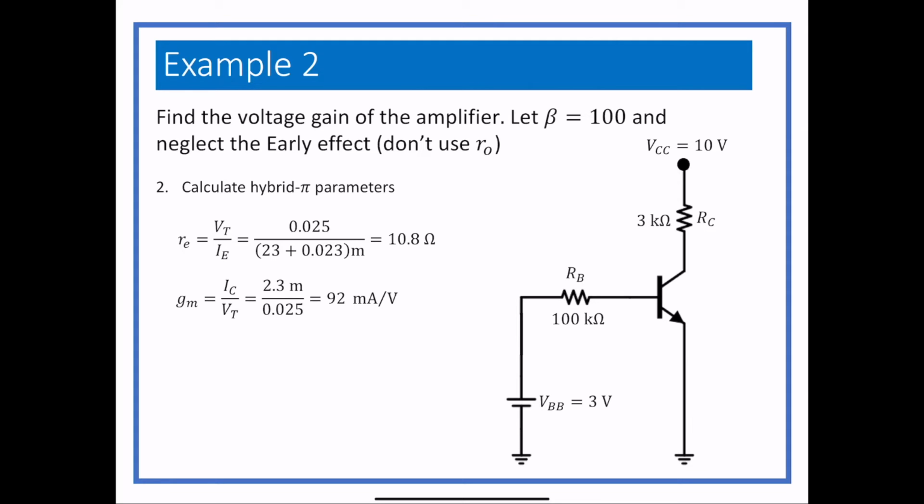That's because IC and IE are often really close together. So sometimes it's assumed that 1 over gm is little re. That's just one of the assumptions that's made because IC and IE differ by so little. But usually I use the actual correct values, unless it's inconvenient, then I don't.